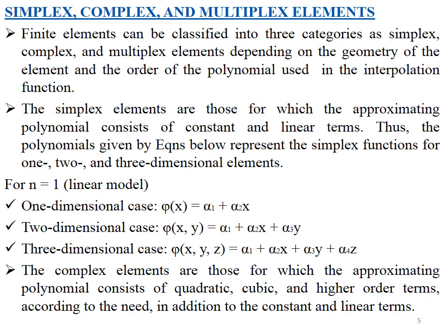Complex elements are those for which the approximating polynomial consists of quadratic, cubic and higher order terms in addition to the constant and linear terms. Simplex elements are of linear terms, and multiplex elements are of some higher order terms.